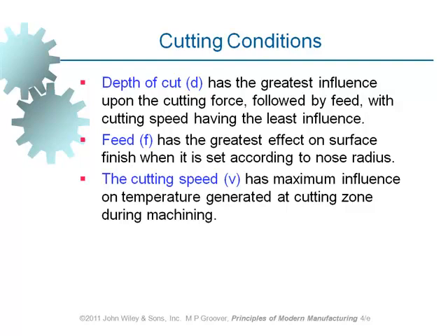Let's move on to depth of cut. How do we do that? We have decided about feed rate. How do we decide about depth of cut? The rule to be used in industry is take the deepest cut, which is allowed by the power of the machine and also rigidity of the machine tool, and work this. The deepest cut, which is possible.